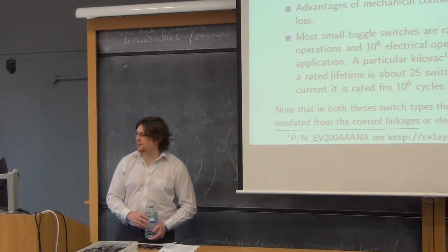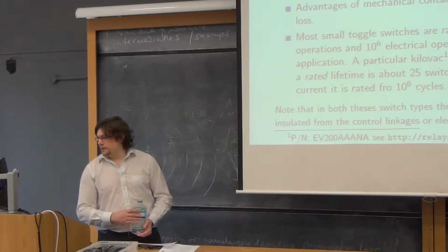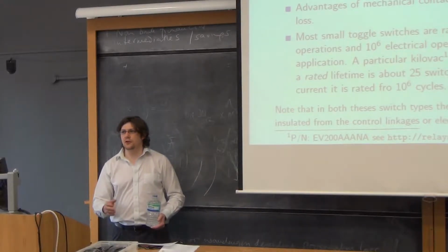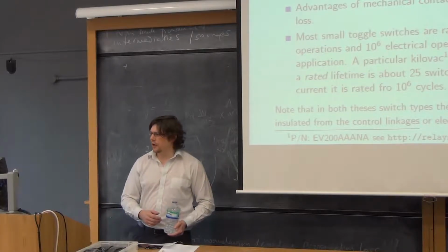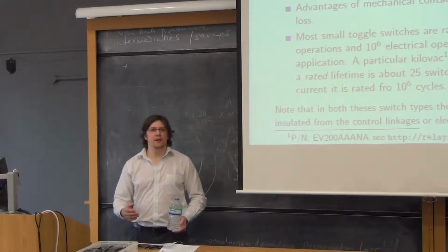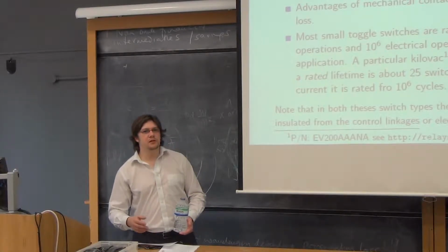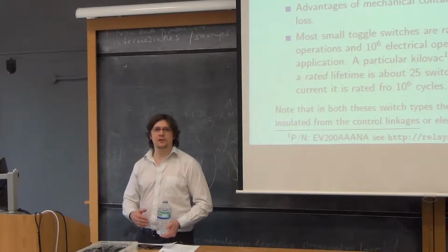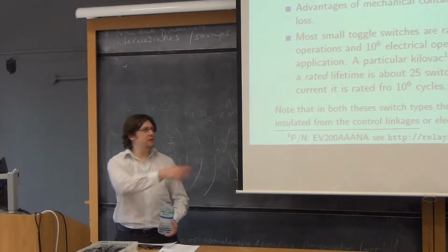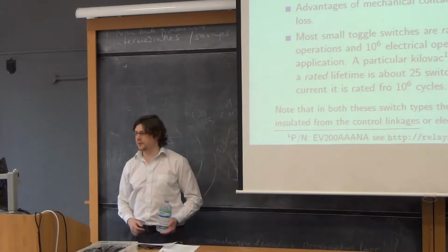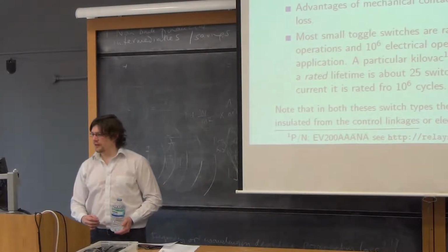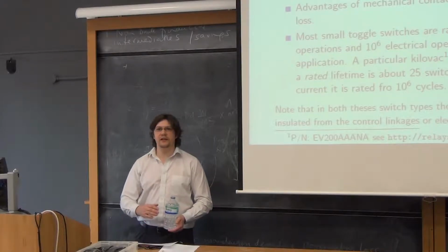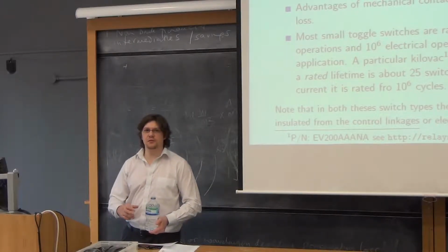So if you were in some, I don't know, electric car situation, and you had a big battery pack in the boot of your car or whatever, and you were using it to drive some hybrid powertrain, and something went wrong, and your safety systems, your ECU, decided to cut the relay between the battery pack and the drivetrain, and it was at full tilt, you'd only get, with the relay that I've given the part number for, so you can look up its specs if you want to, 25 cuts, and then the relay is dead, because breaking that current oxidises the terminals and upsets the relay.